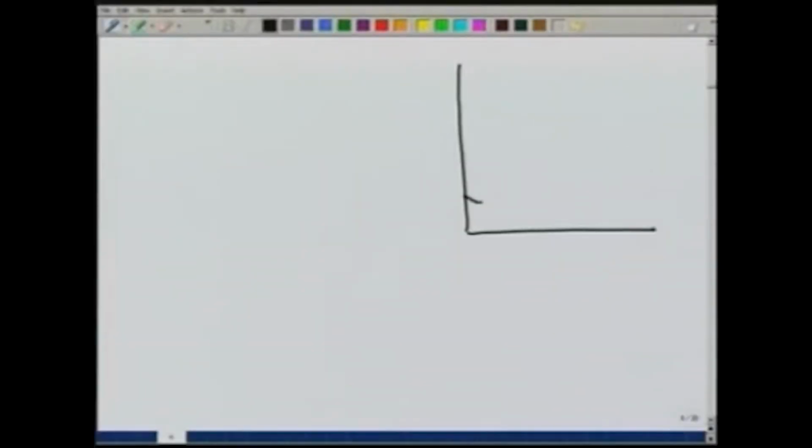We have already discussed 3 different methods of separating the base flow. There is another empirical method which is sometimes used to locate the end of the direct runoff. So, if this is the total runoff, the starting point A is easy to see because this is the point at which the hydrograph starts rising. The ending point D typically is estimated by eye to see where the base flow has started and direct runoff has ended.